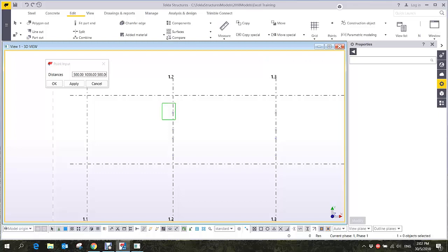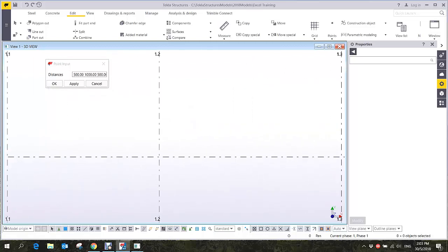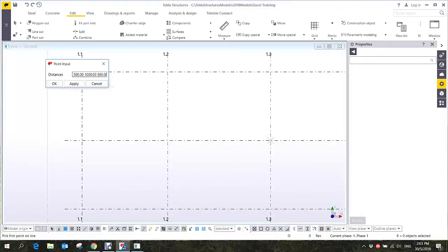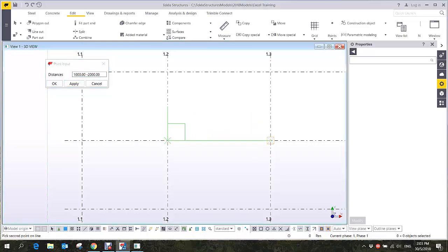Okay, now what if I want to have 1000 from here, 1000 from here, and then from here also 1000. So 1000 from here, and then back here 1000. So what value do I need to put here? Again, parallel to 2 points. So from here 1000 space minus 2000. Yes, correct. So 1 2, because it will start where it ends. That's why it's 2000. Clear?